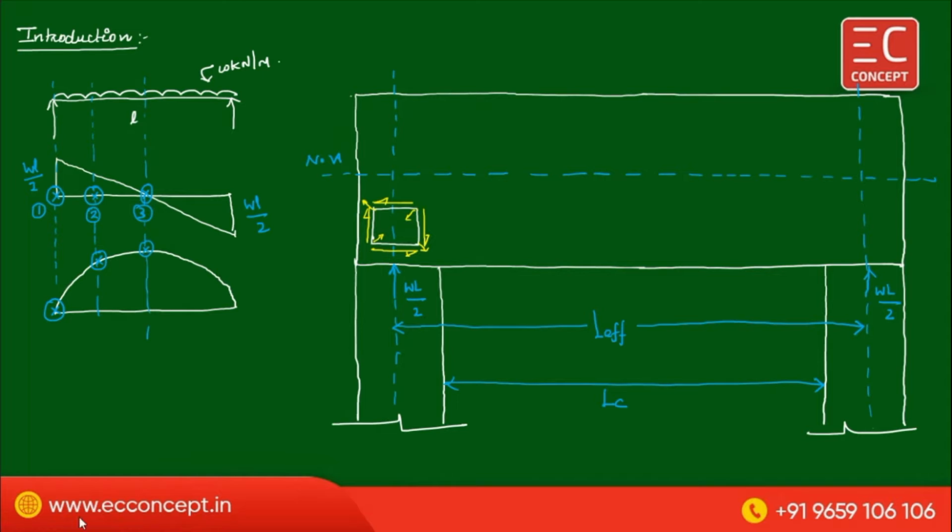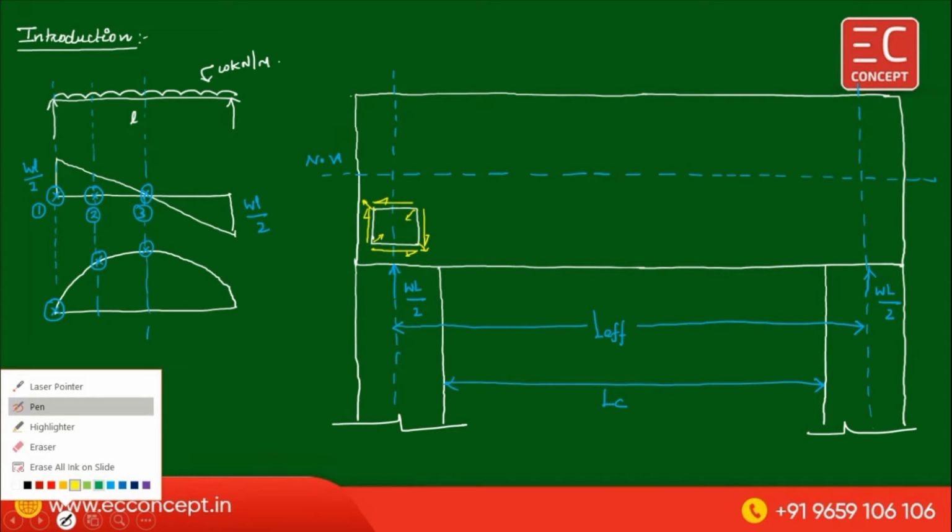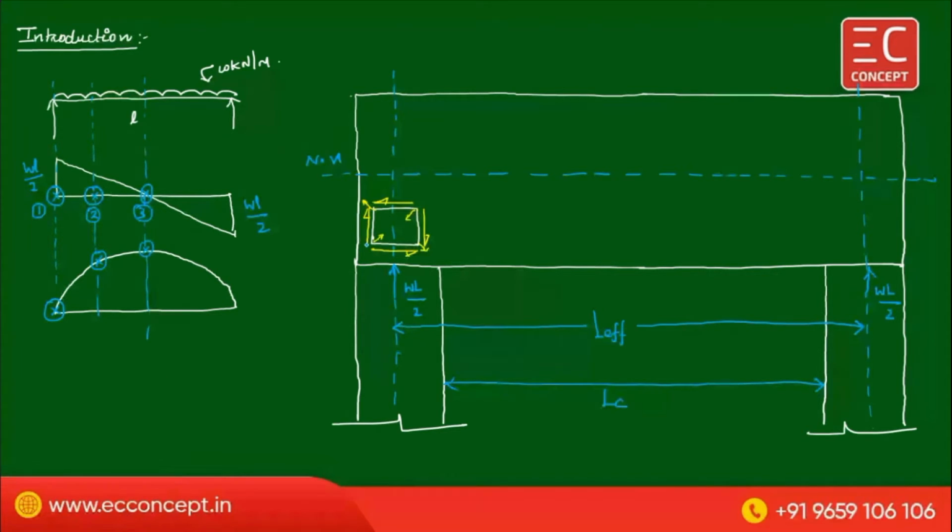So in this direction there was a tensile force acting. Therefore the failure happens along the diagonal. The stress corresponding to this is sigma 1. This is the manner in which the stress is acting. And the plane at which the failure happens, we call it the major principal plane.